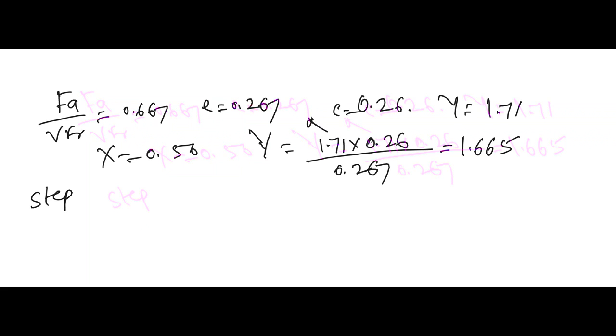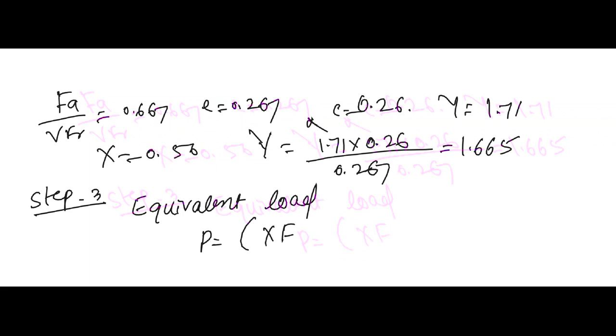Equivalent load. So P equal to what? X into V into FR plus Y into FA, into CS. Now we substitute. X is 0.56.